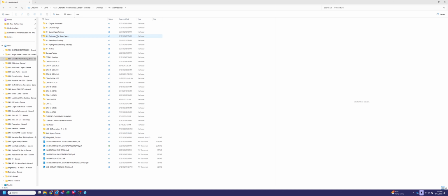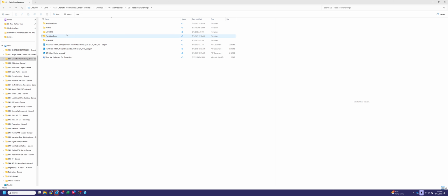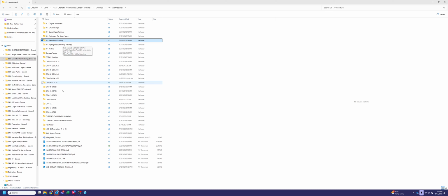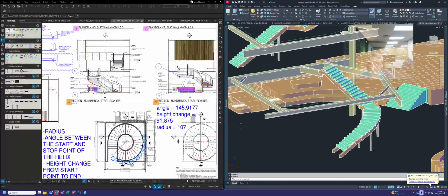It's very time consuming to do it that way, but by the time it gets approved and we get either a laser scan or a CAD from the steel vendor, that actually makes things way easier because you can really just work off of what they give you versus trying to use an architectural drawing and make ends meet. In the case of this one, I had a lot of conflicting things, like reveals that were shown at a quarter and then shown at a half in a different view.